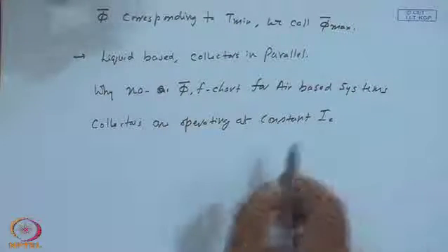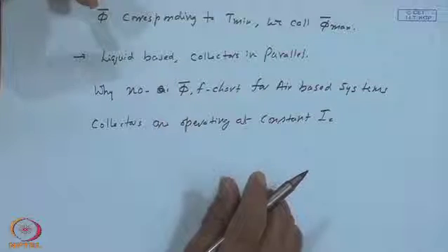Simply, if the ambient temperature average is, let us say, 15 degrees C, you may have the minimum to be 12 and maximum to be 18. So, if you calculate the critical level between 12 and 18, there will be good variation. Consequently, my utilizability may be different on different days, at least as far as the ambient temperature is concerned. However, the differences when averaged, once again, one may be an underestimate and the other may be an overestimate. Consequently, my phi bar max corresponding to T A bar may be an acceptable number, but somebody can verify these things.